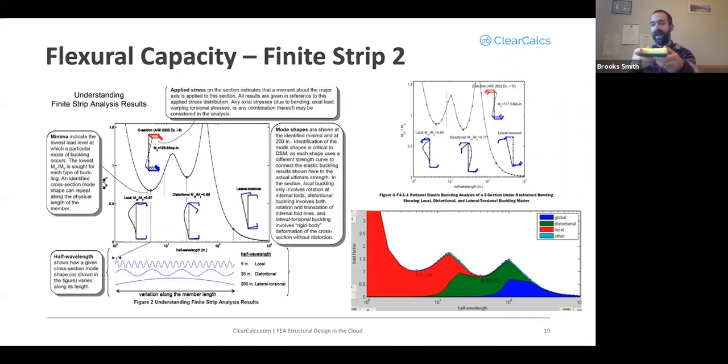If you restrain that global buckling, however, and you bend it, you'll see little divots of curving happening in the middle. That's a much smaller half wavelength. That's your bending that's occurring over a much smaller length. So essentially, finite strip analysis is doing that type of analysis, seeing over every possible half wavelength what is going to be the likelihood of divots bending forming.